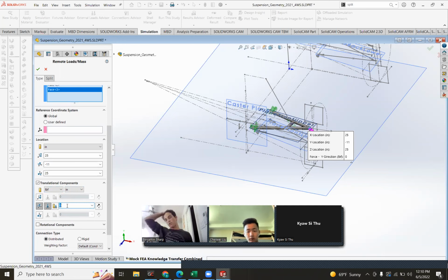So the force we're seeing is usually for a bottom impact, 3 Gs by a quarter of the car. We've also said half the car before, or 2 Gs by the whole car. It kind of depends on what your thinking is for the year. And I'll write this out in the suspension Bible as well. But hopefully we're going to have some concrete data to derive these loads from soon. And hopefully we see that all of our loads historically have been a huge overestimate.